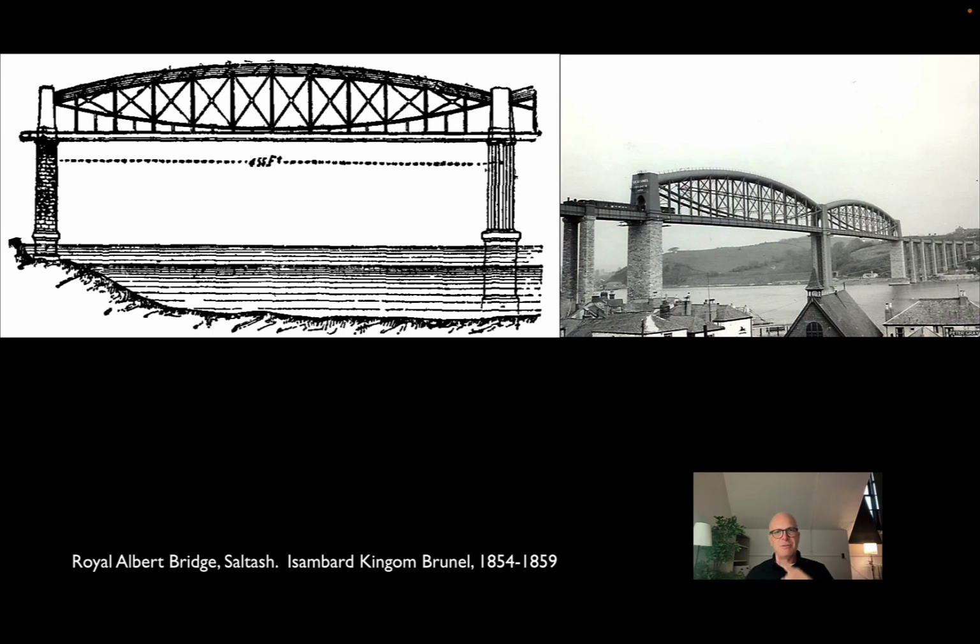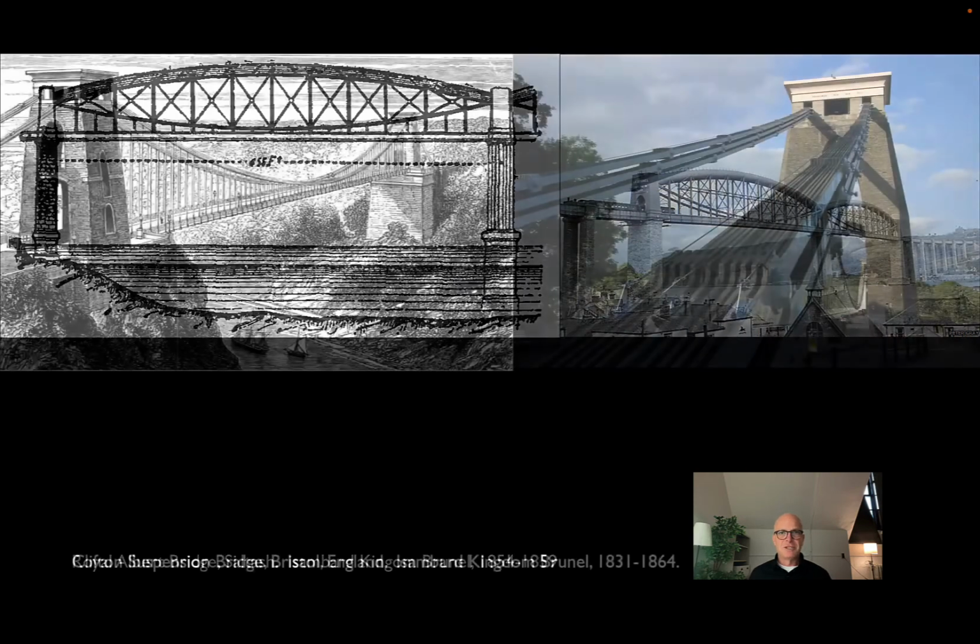The tension arch is the positive curvature or the smiley face. The compression arch is the negative curvature or the frowny face. The thrusts on those two cancel each other out. The compression arch wants to push the towers apart. The tension arch wants to pull the towers together. It therefore requires no buttressing and it requires no backspan like a suspension bridge would. It's an odd-looking bridge, but nevertheless, the principle is absolutely sound. And as you can see, the bridge did its job, right? It certainly spanned successfully.